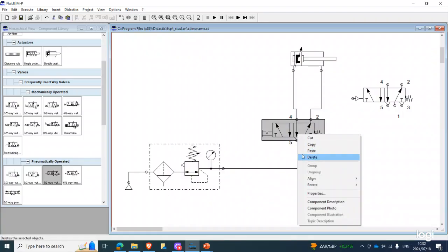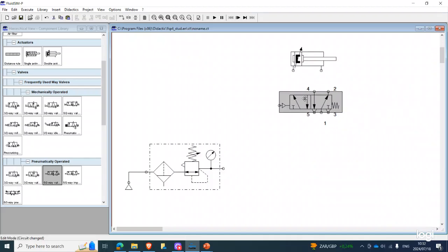It should be pneumatically actuated, so we're gonna use this 5-way valve. The connection here is the same, and we can also directly connect this to our compressor.